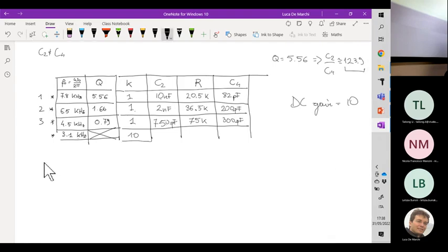Again, for the first order stage, C times R2 is equal to 1 over omega null, and the gain minus R2 over R1 should be indeed equal to minus 10, to achieve the desired DC gain. This is, let's say, the amplitude, the modulus of the DC gain.